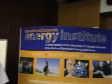I would say that the more instructive case to illuminate some of the questions that you're asking is what we are working on the ETL side with zinc oxide, because we can tell a lot more about the physical properties. I didn't talk as much about that because I just had to pick something. But I would refer you to AJ over there, who's doing a lot of that work. We have looked at differences in carrier concentration, differences in mobility of zinc oxide, and what impact that has on how well we're able to get carriers out.